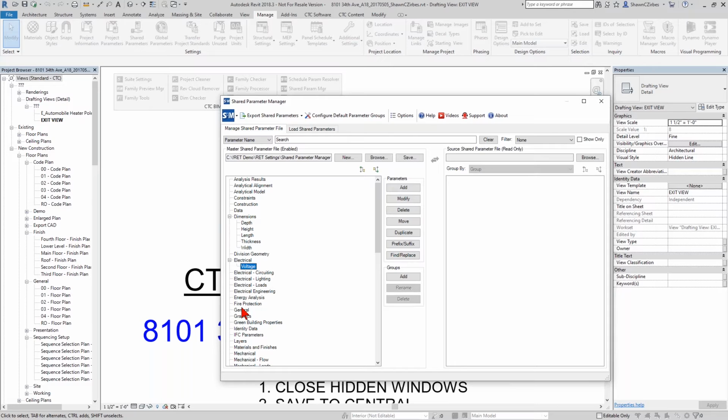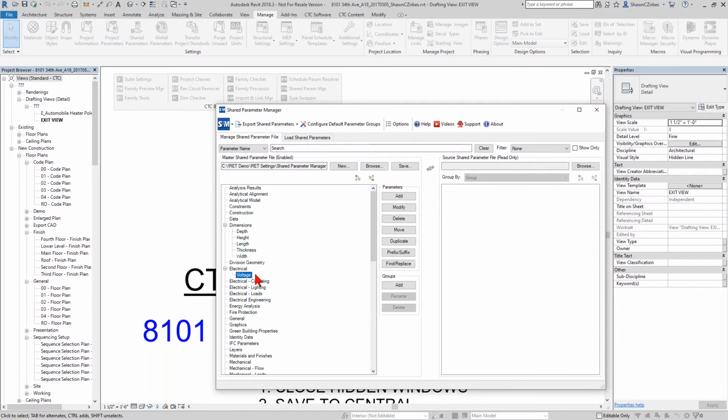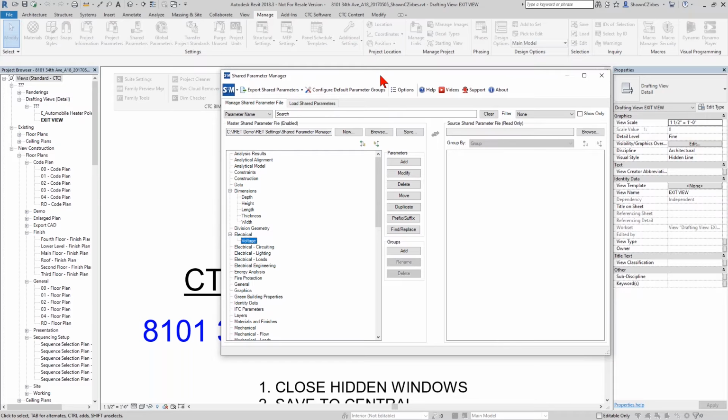So what this means, though, is that if you have an entire library of content based on the old voltage, based on text, you will have to go hand touch that content to fix it and update it to make it correct. Revit doesn't magically know what you want to do there in those other files. So you will have to make some changes there. That said, I do have tools that can help you with this, right? I've got a tool specially designed for helping you do shared parameter management, but also a tool specially designed for helping you fix your families and fix your schedules that are in your projects, right? So there is an entire collection of tools. Don't be afraid that you can't do it. You can change your mind on a parameter standard and implement that in a very short amount of time.